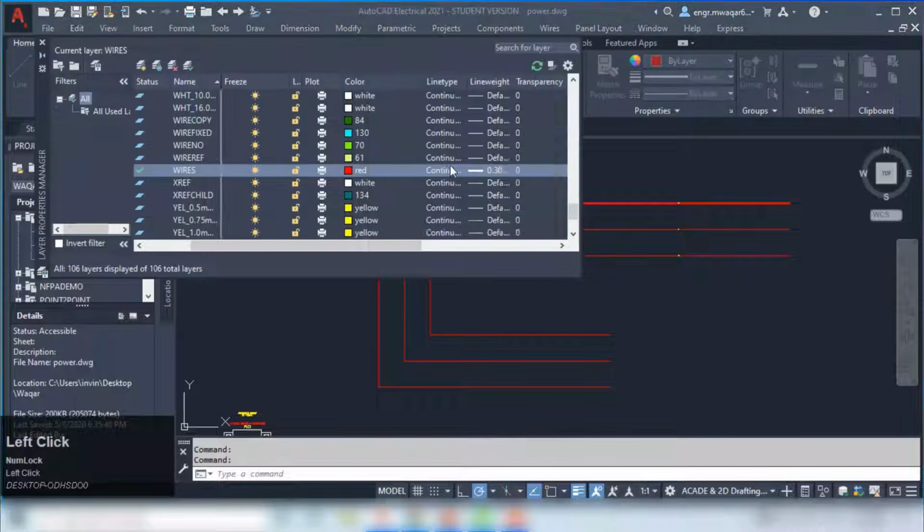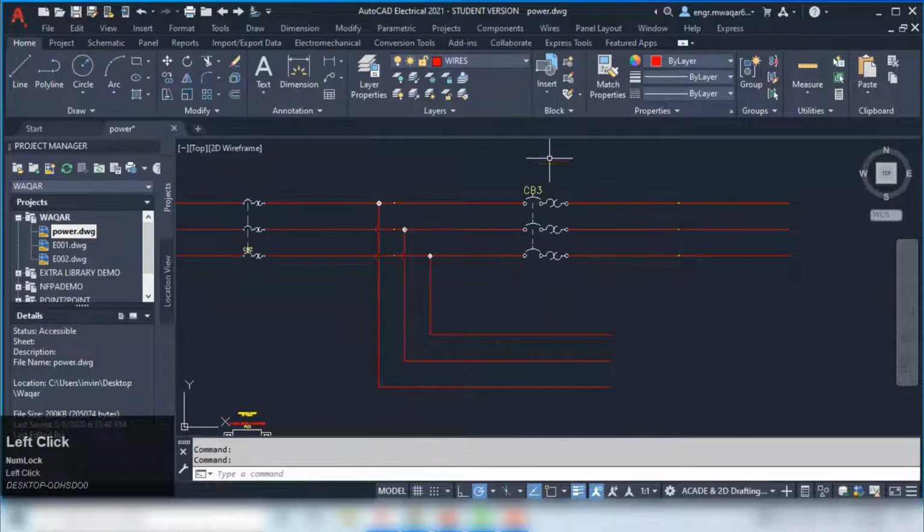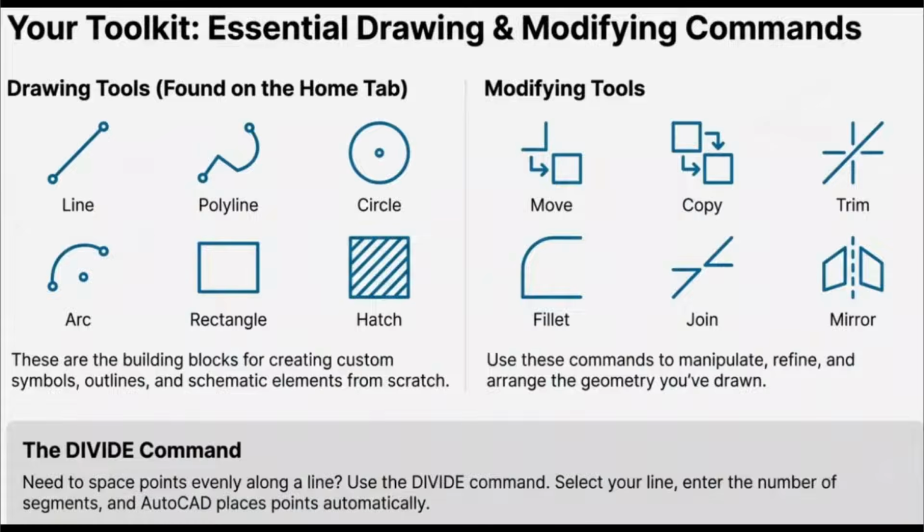Okay, let's quickly touch on the geometry. We are still in AutoCAD, so we rely on those fundamentals like line, polyline, arc, circle. Exactly. We rely on the basics and the standard modification commands like move, trim, copy, mirror. But there's an extra layer of intelligence there. There is. The strategic point is that when you use a command like trim on an AutoCAD SmartWire, the software automatically cleans up the underlying wire data and maintains continuity. It's using a base command, but applying electrical intelligence.